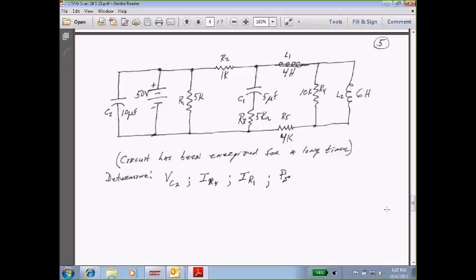Okay, now let's go to that first junction and use the current divider rule. We've got 20 milliamps coming into the first junction. R1, which would be I1. We've got 5K of resistance going that direction. Now, if I look going the other direction, I've still got 5K going around the rest of it, so it's just going to divide evenly. So I would have 10 milliamps for IR1, and that's one of the answers that we were asked trying to determine. So the current for R1 is 10 milliamps.